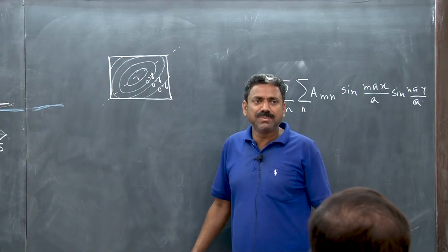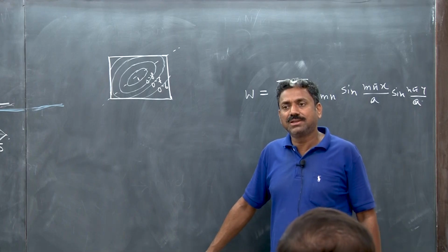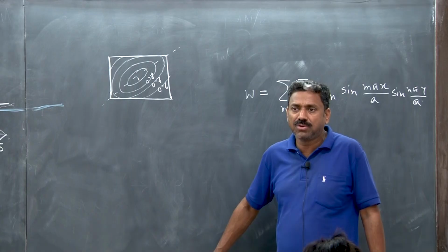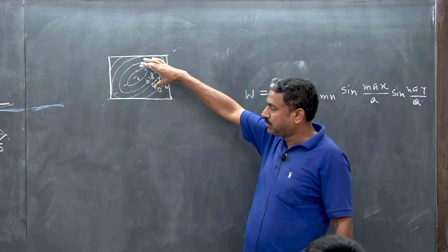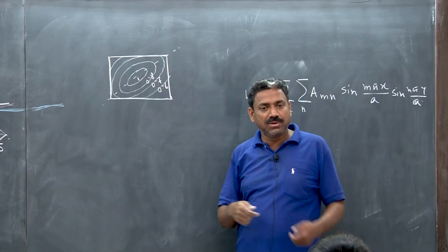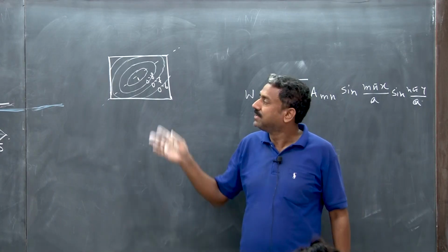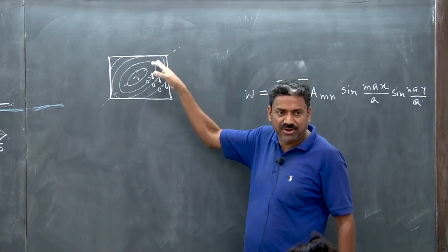That is what happens when you buckle under shear: one diagonal is under tension, another under compression, and they are mutually perpendicular to each other, right? So it will be shrinking along one, whereas it will have a little extension in the other direction. You see, that is what is essential. So, this is a symmetric buckling, because it is symmetric, right?